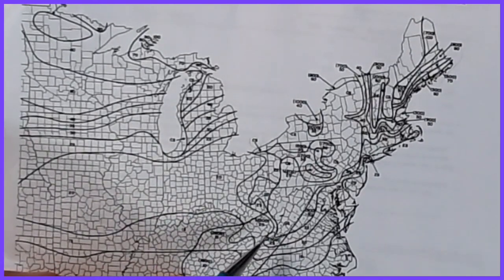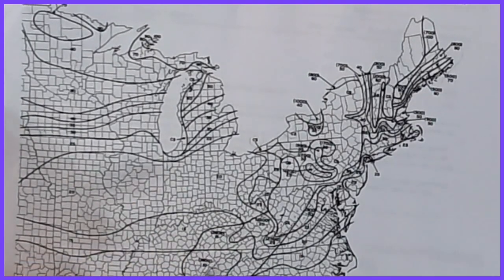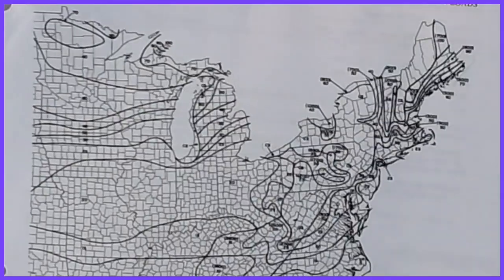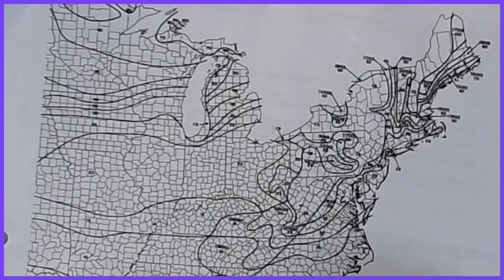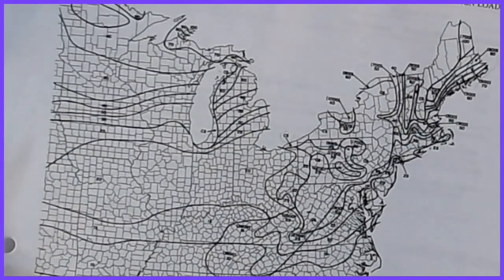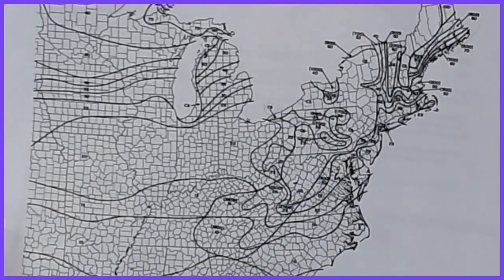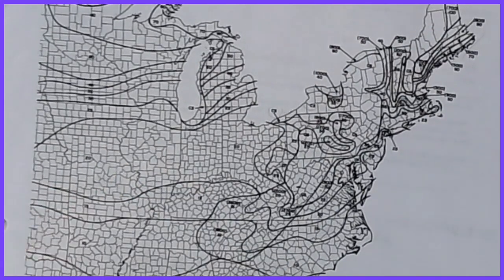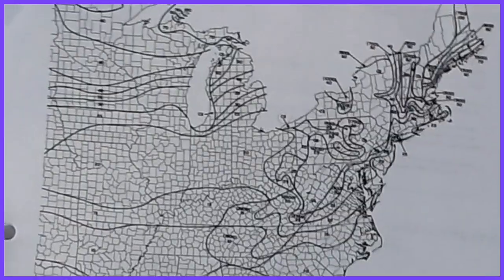If you're working in an area that has a CS ground snow load, then you need to be talking to local authorities to find out what their design parameters should be historically. It can be substantial. It can be much more than even the hundreds in some cases. So that's why that's called out on the maps. ASCE 7-10 basically punts on numbers in those specialized regions. But for the rest of us out in the Midwest, it's pretty easy to use these values, and this method will work very well for those.